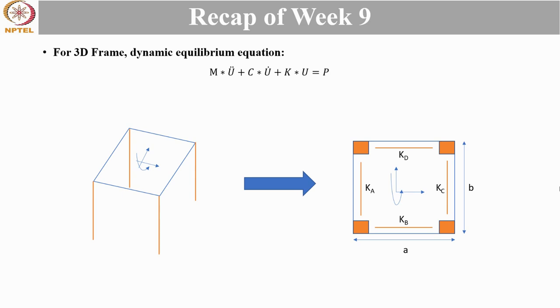Now, how is 3D analysis seen? In this, there are both translational as well as rotational degrees of freedom. Fixing one degree of freedom to unity and the others to zero, we learned how to develop the mass and stiffness matrix. In planar view, we get an idea of which columns or series of columns contribute to opposing motion along one degree of freedom.